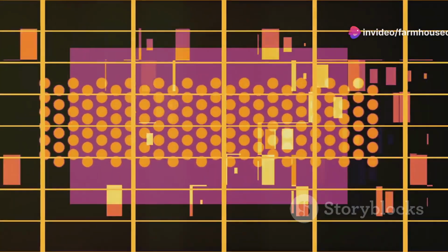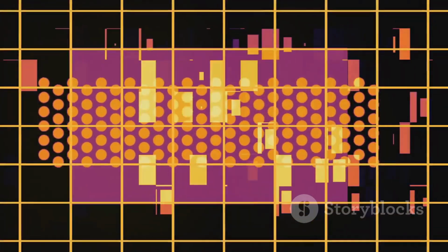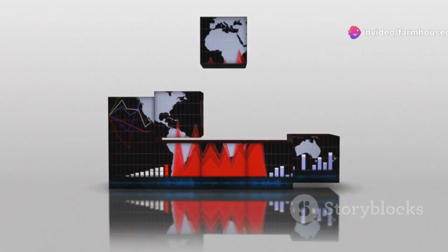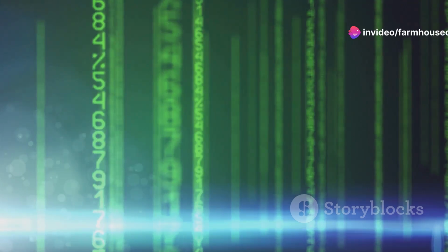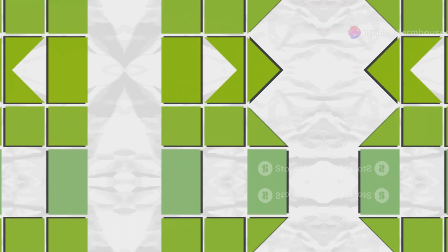This adjacency is crucial as it allows us to visually identify groups of 1s or 0s, representing minterms or maxterms. These groups help us derive a simplified Boolean expression for the function. The visual nature of K-maps makes them an intuitive tool for simplification.